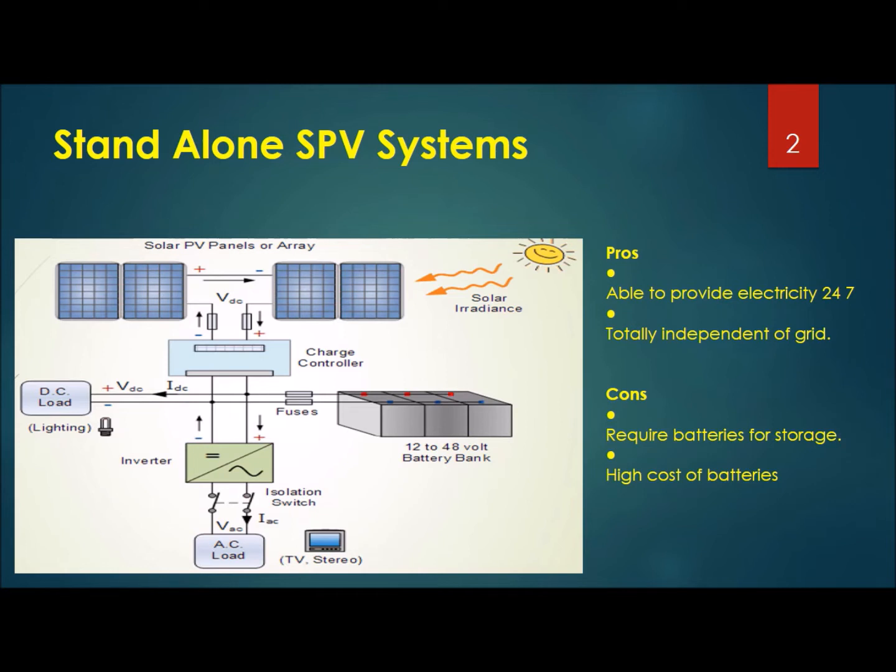Stand-alone solar photovoltaic systems. Solar photovoltaic based stand-alone systems used in islanding regions are generally designed as shown in this slide, which require some additional attention. The standard voltage level of such applications is generally in the range of 220 to 250 volt AC. As a result, the voltage level of the DC link of the DC to AC inverter that feeds these loads needs to be maintained around 360 to 400 volt.